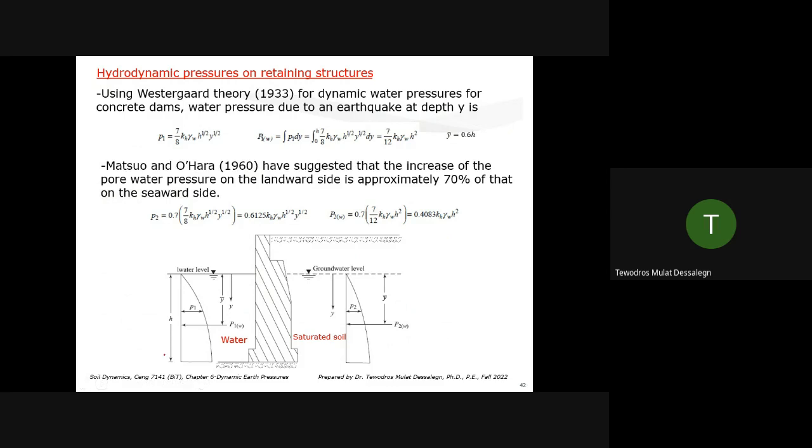The same phenomenon happens from this side. This water during an earthquake may have tidal formations. There is a convective and impulsive response of water. The top portion of the water usually can oscillate. It can make tides like this. In some cases, it's like sloshing back and forth.